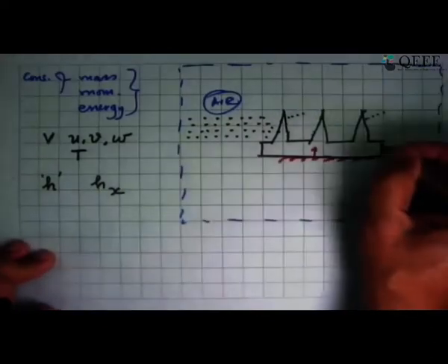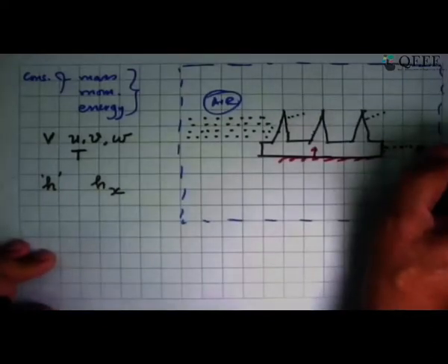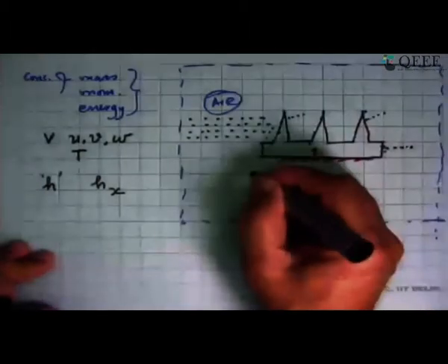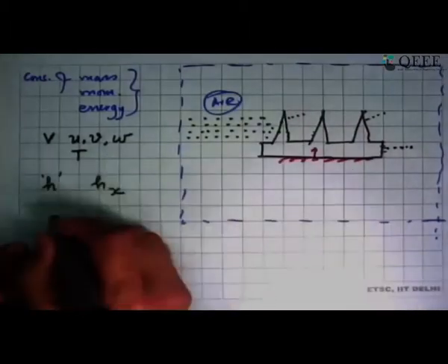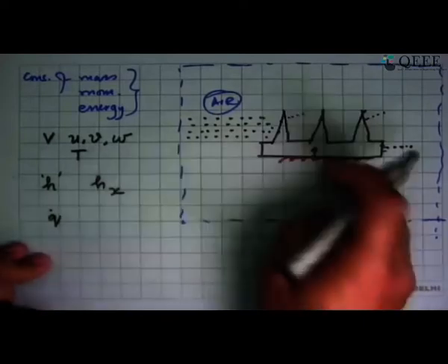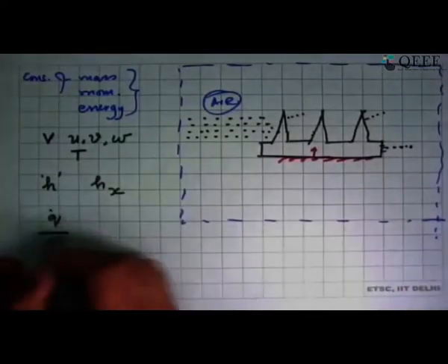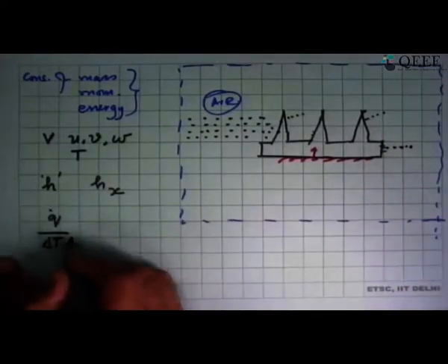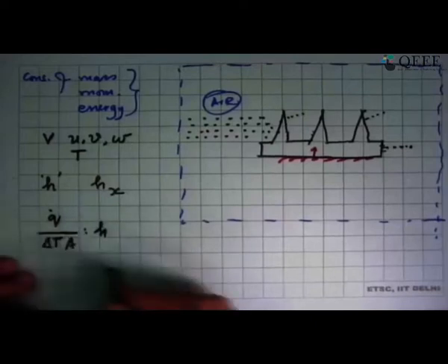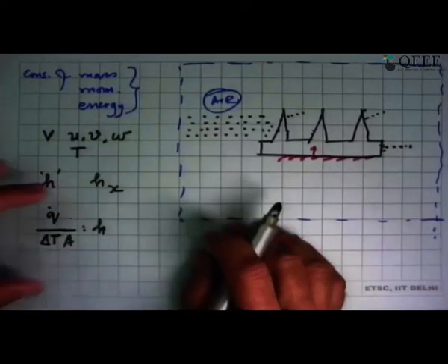Its temperature we have known, so we know what is the heat transfer rate from here, and then we integrate it over the entire surface and then get what is the total Q dot that we were getting over there. That divided by some representative delta T into A, this will be the value of H. So without doing experiments, we got this correlation.